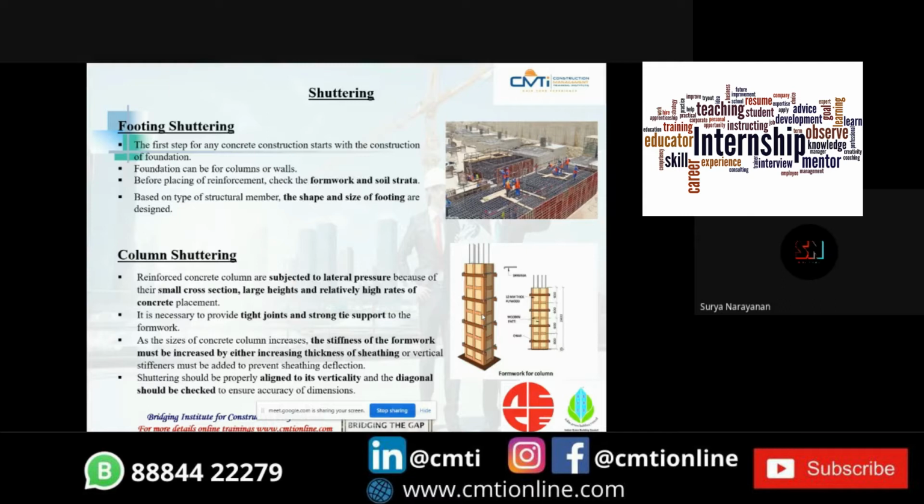So next is column shuttering. Columns are subjected to lateral pressure because of their small cross section, large heights, and relatively high rates of concrete placement. Tight joints and strong tie support should be provided to the formworks. As the size of the column increases, the stiffness of the formwork must be increased by either increasing the thickness of sheathing or adding vertical stiffeners to prevent sheathing deflection. It should be aligned for verticality, and the diagonal should be checked to ensure the accuracy of dimensions.